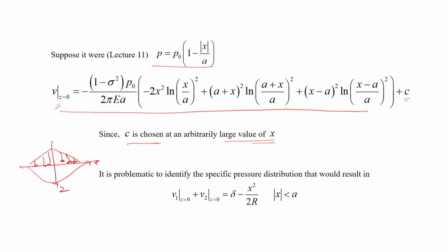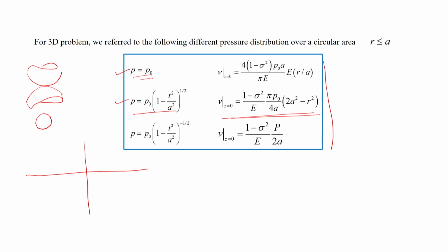have obtained for this different type of pressure distributions, okay, directly for solving this cylinder problem in which the two cylinders are in contact. So, that was not a problem for the spherical geometry. Whatever results we obtain from this in the circular or spherical geometry for the spheres in contact from the results of elastic half space, those results we could directly use, okay, for understanding what will be the contact radius, or what kind of deformation profile will be there for these spheres.